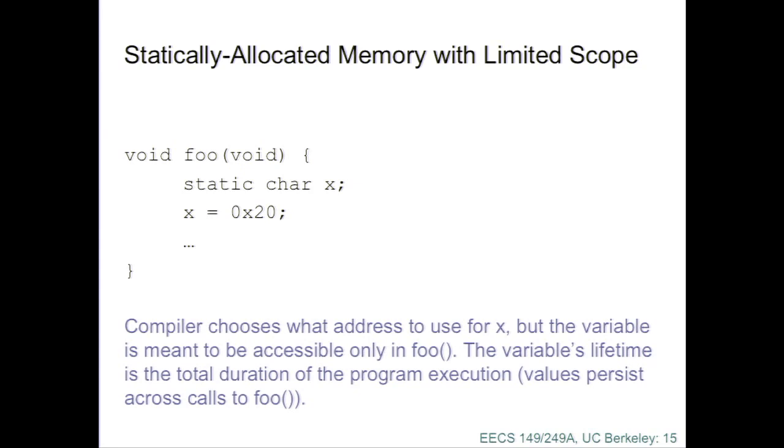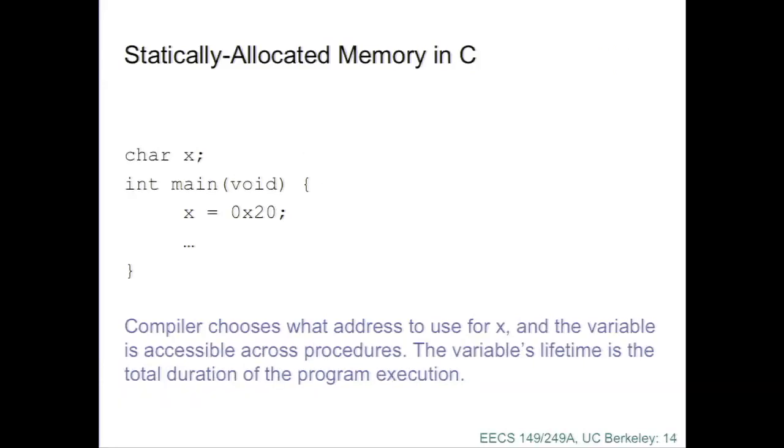By the way, there's one real trickiness that comes up in embedded systems, which is that in ANSI C, you can initialize the static variable X to an initial value. So when is that initial value put into that memory location? When it runs is one conjecture, but usually not, actually. It's in the binary. So it's put into memory when the program is loaded. When your bootloader copies the program into memory, the initial value goes into the memory.